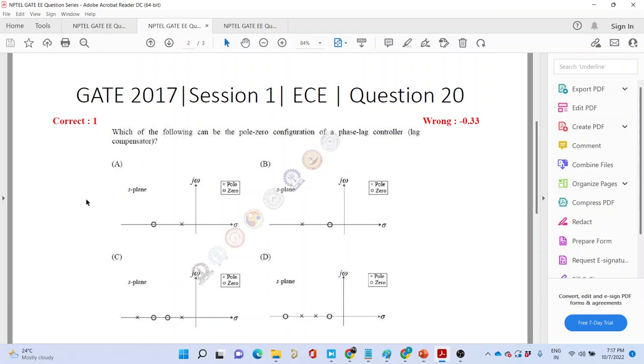Because at the end of the day you are looking at the steady state response, and also the transient response, but the one which is decaying down faster, you're not worried about it. The oscillations which are going to last longer, you're worried about that, right? Say there are two poles, one contributing some oscillations, and the other pole also contributing to some oscillations which are decaying down. Both oscillations are decaying down.